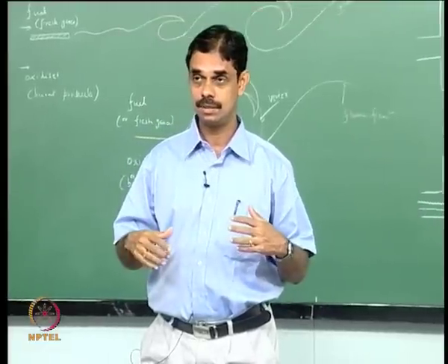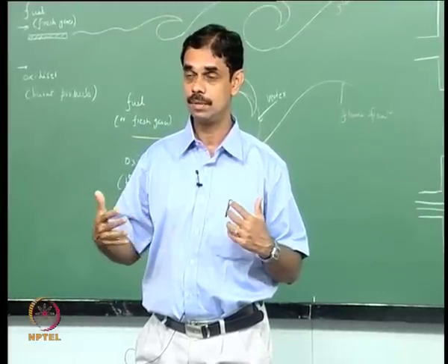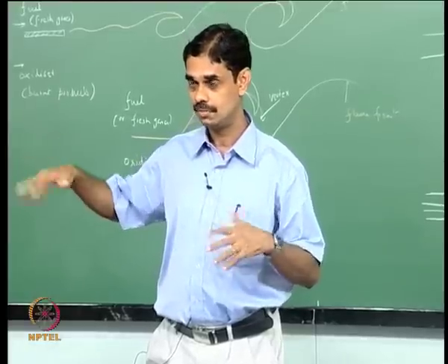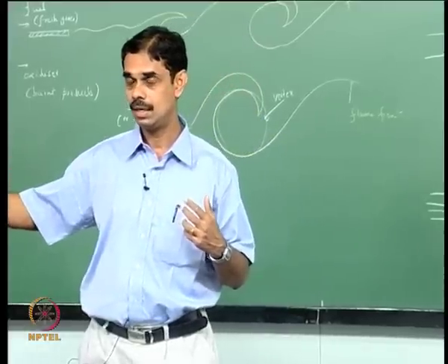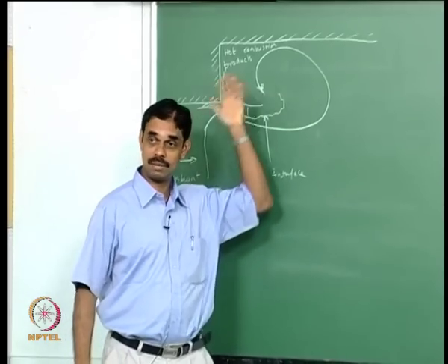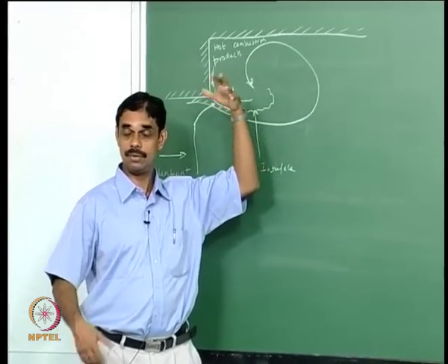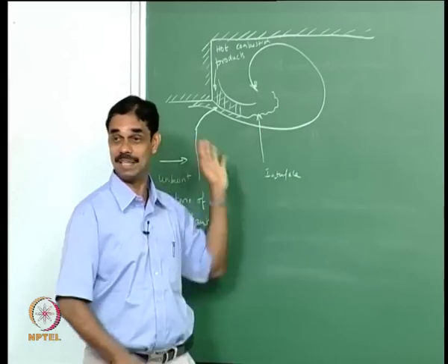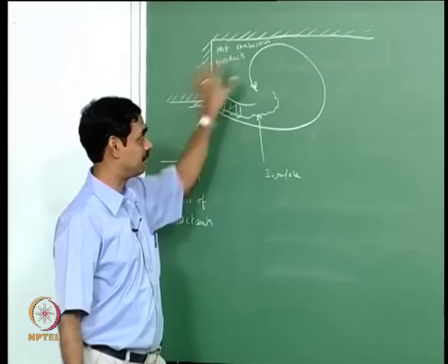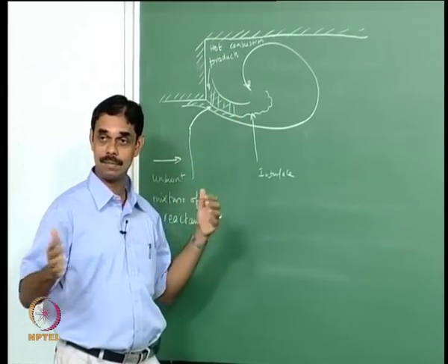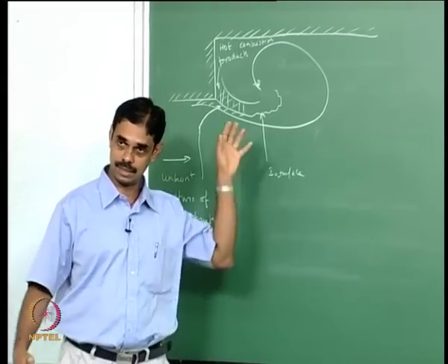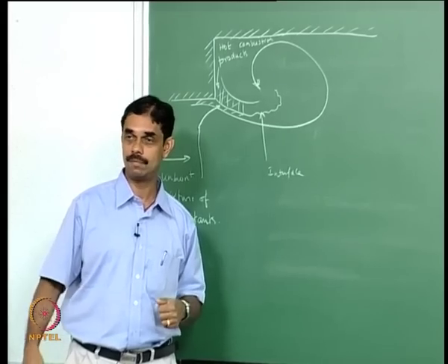First, in the 60s and 70s, people came up with models for how these coherent structures appear fluid mechanically, and now there are calculations. So you have a CFD model for all these things, which you couple, or you can have a full compressible solver which will capture everything if you are rich and you have big, fast computers. But if you don't, you can solve for the hydrodynamics separately, have some asymptotic expansion, and then input this into the acoustic solver and do a coupled solution. So people have solved for it.